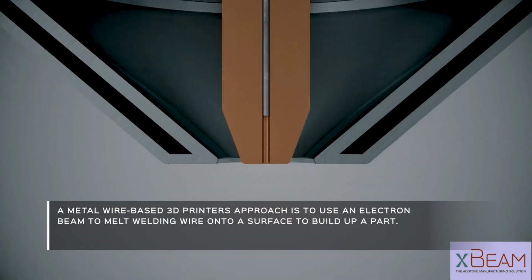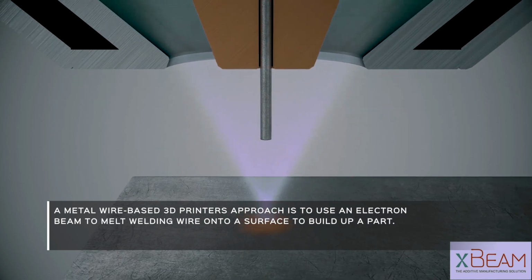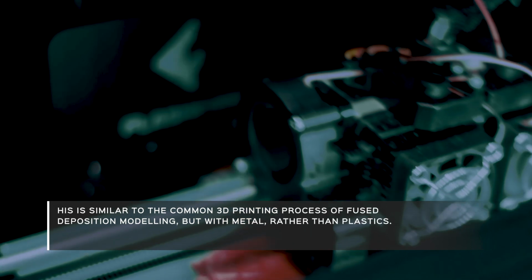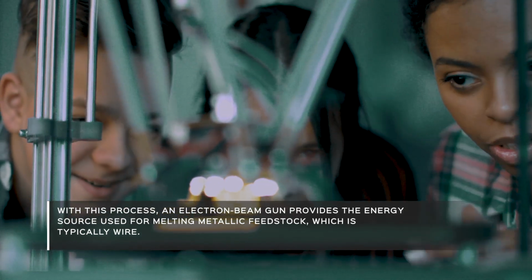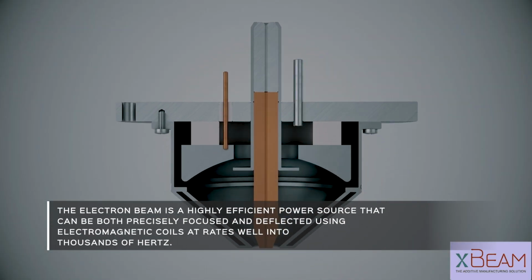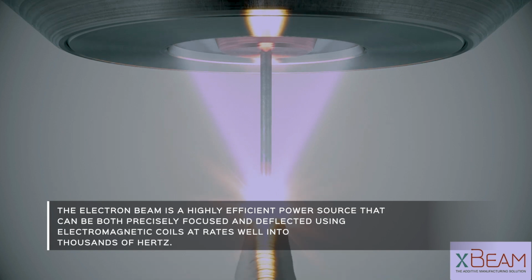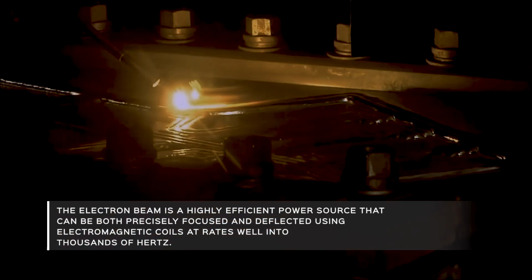A metal wire-based 3D printer's approach is to use an electron beam to melt welding wire onto a surface to build up a part. This is similar to the common 3D printing process of fused deposition modeling, but with metal rather than plastics. With this process, an electron beam gun provides the energy source used for melting metallic feedstock, which is typically wire. The electron beam is a highly efficient power source that can be both precisely focused and deflected using electromagnetic coils at rates well into thousands of hertz.